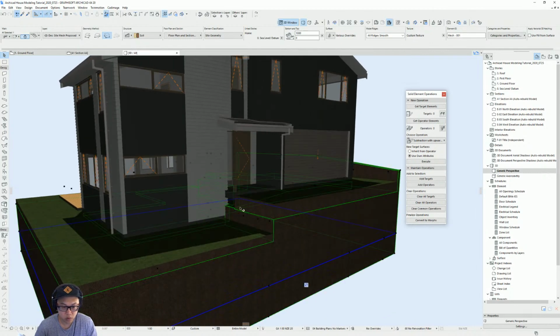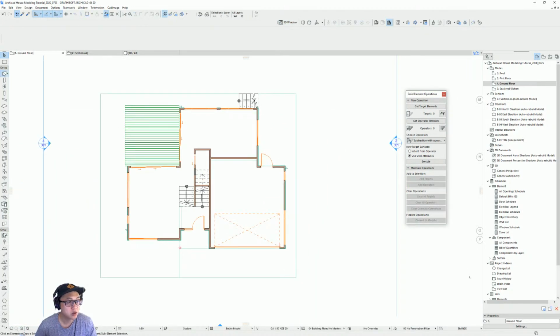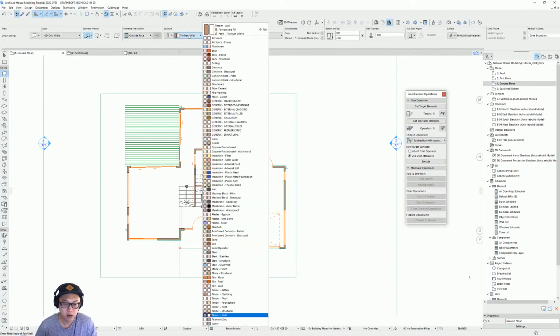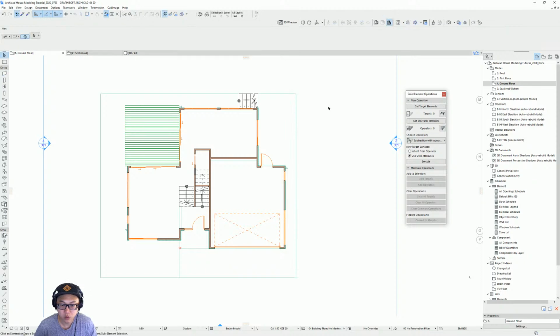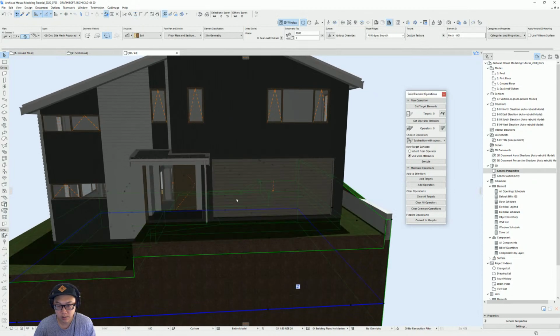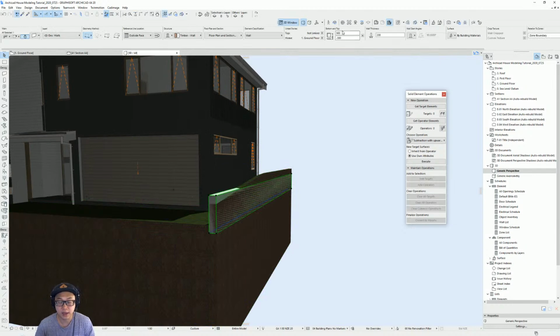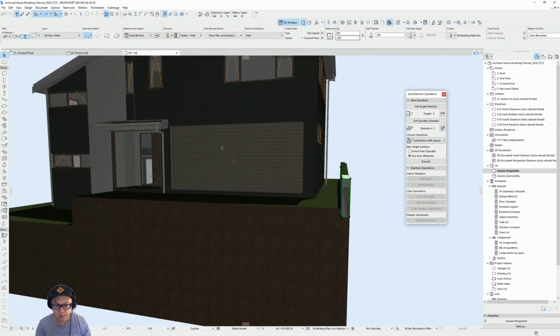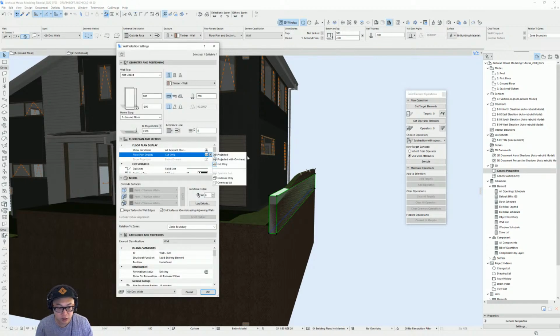I need to have some type of walls there. Wall tool. And number bigger, 200. Why is it not showing? I think it's because it's too small. Like I said in previous video, when you create a floor plan, it actually creates a cutting line. And because this one is not enough to intersect with that cutting line, that's why it's not showing. So the way to show that is to go into the setting and do project it.